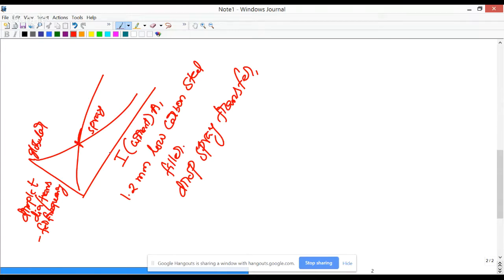If you keep on increasing current above the spray transition, what happens then? The Lorentz force formed in the droplet becomes extremely significant, and the droplet diameter detached from the electrode tip decreases significantly. You would end up transferring the droplet not as a single free flight droplet, but the droplet diameter is so small that you can't distinguish individual droplets at all. So it will be a continuous spray, and we term this a jetting spray.